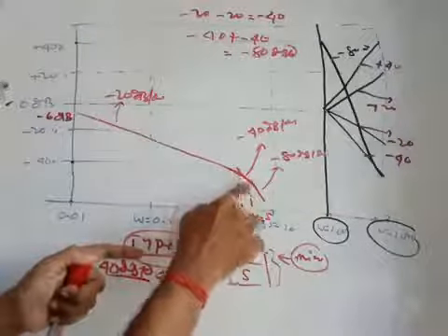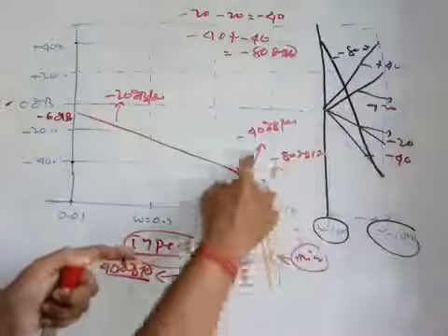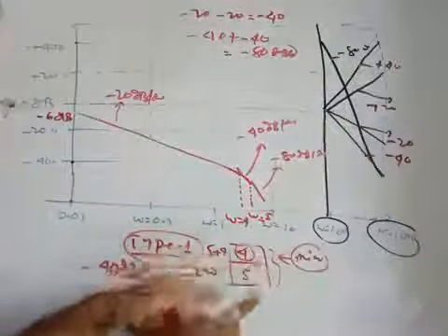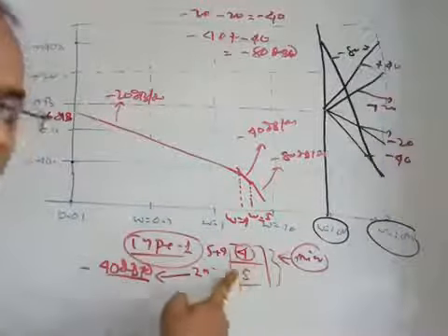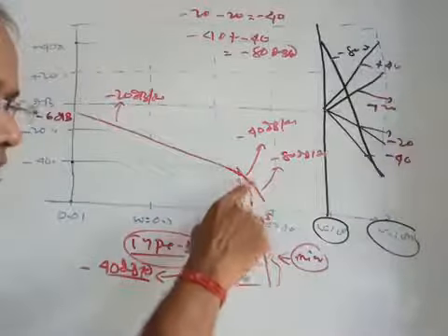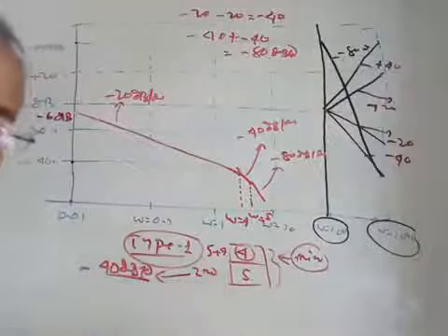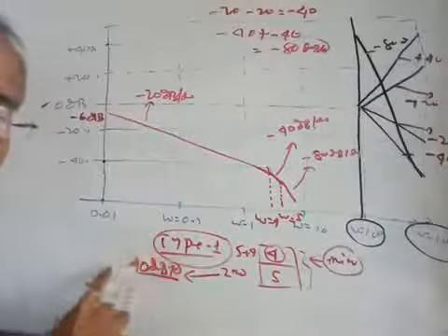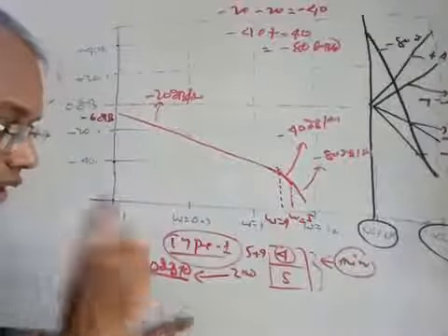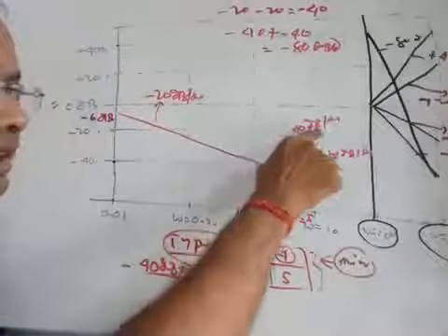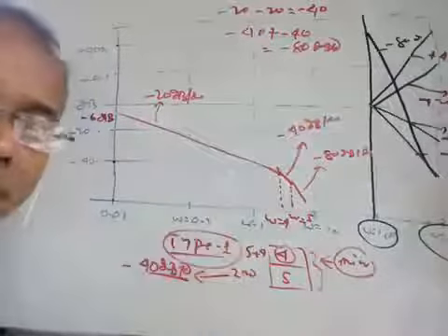So the resultant slope is made parallel to the minus 40 dB per decade line, and this goes up to the next corner frequency. Here there are only two corner frequencies, so we get the next corner frequency, which is 5, and this goes up to 5. Once it reaches 5, it sees this is a second order pole. So it has a slope contribution of minus 40 dB per decade. The previous slope was minus 40 dB per decade also. So minus 40 plus minus 40 means minus 80 dB per decade is the slope.